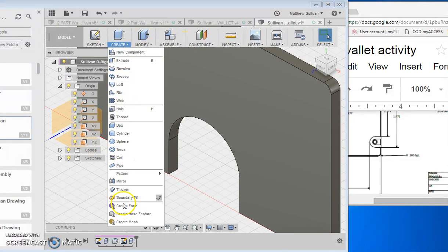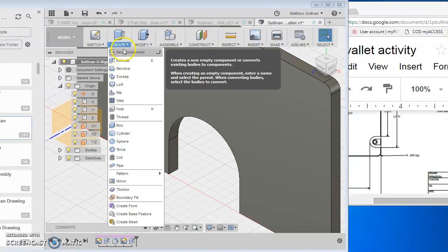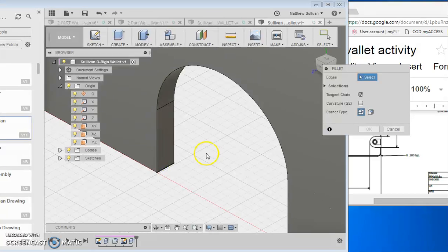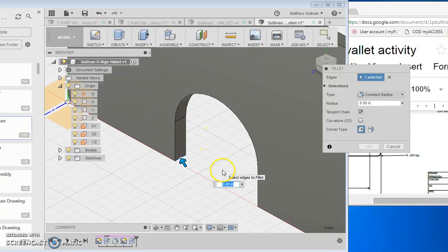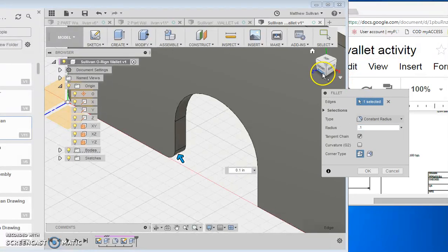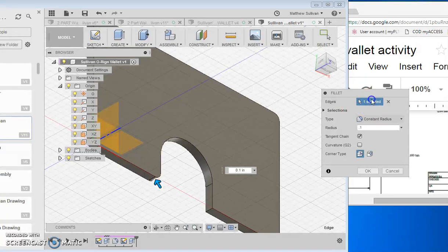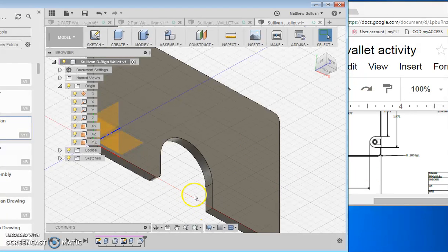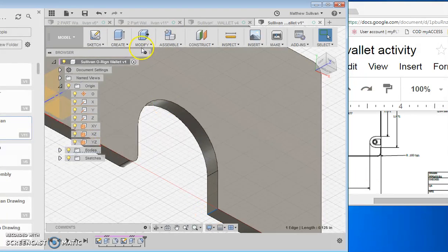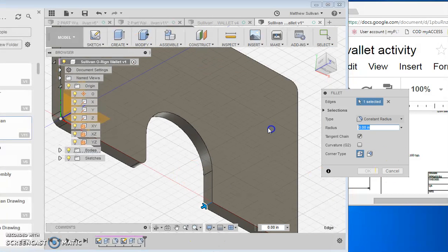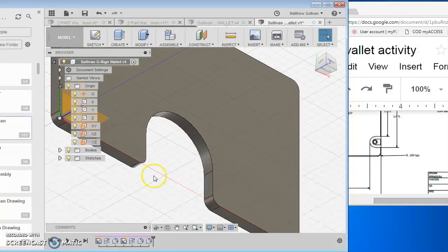Create radius, center modify, fillet. Sometimes when you type in a value off the bat, it doesn't allow you to select multiple. Yeah, so your selection is limited now. You can't select it again. So sometimes making all of your selections and then typing your value can speed the process up.